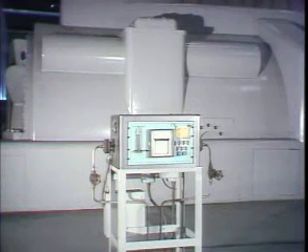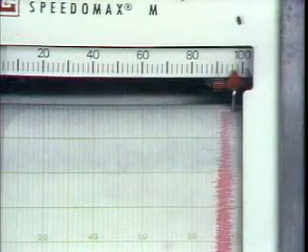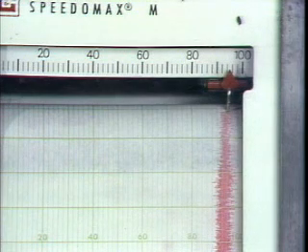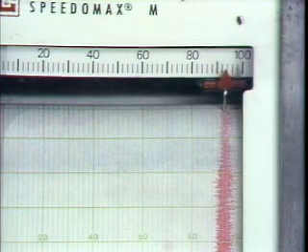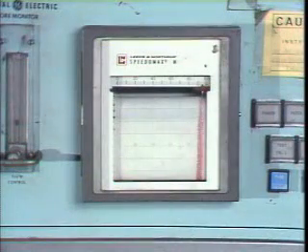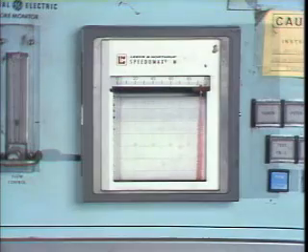Inside the generator cooling system, a small sample of the circulating hydrogen is forced into a device called a core monitor. At predetermined intervals, the core monitor measures the concentration of particulates in the hydrogen and records the measurement on a strip chart recorder. If the concentration of particulates is significantly different from normal, the core monitor usually initiates an alarm. Depending on plant procedures, the generator may have to be shut down to prevent damage.